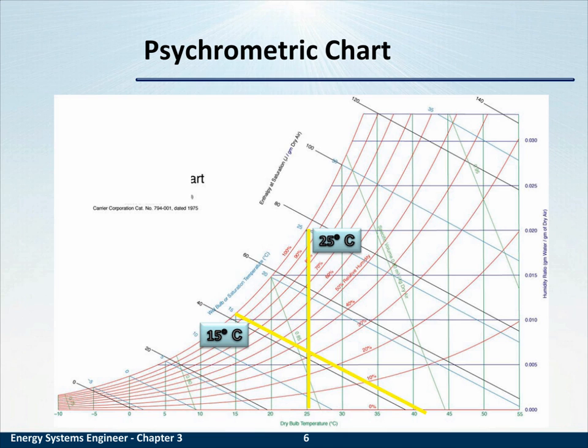You plot the wet bulb temperature, you see across the wet bulb or saturation temperature in the upper left corner of the graph. Draw a line where it says 15 degrees C. That intersection is the relative humidity, and it's 35% relative humidity. If it were drier, the wet bulb temperature would be colder.